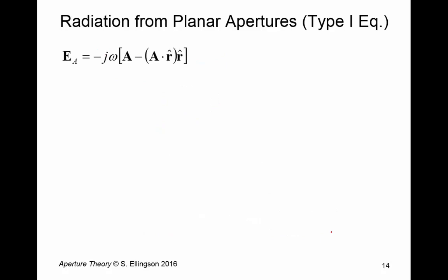So the reason I do that is because now we can see some simplified expressions. So let me work this through. The electric fields resulting from these equivalent electric currents, because they're from electric currents, I'll use subscript A here, we know can be calculated in this way. This is the far field approximation again. Remember this.